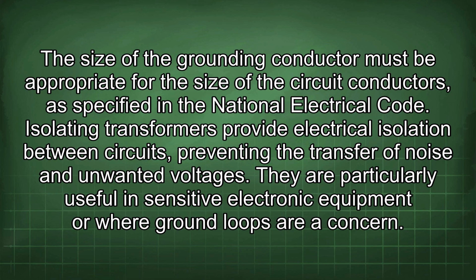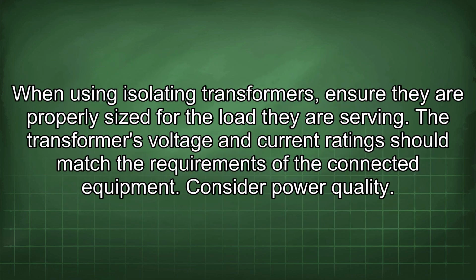They are particularly useful in sensitive electronic equipment or where ground loops are a concern. When using isolating transformers, ensure they are properly sized for the load they are serving. The transformer's voltage and current ratings should match the requirements of the connected equipment.